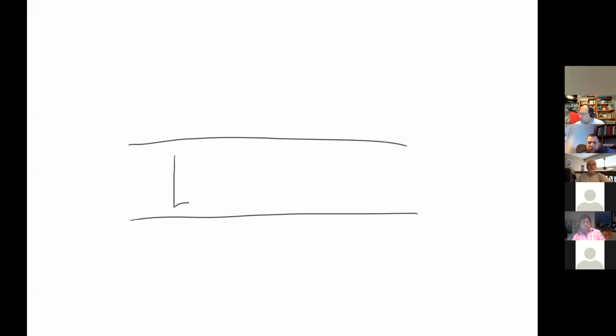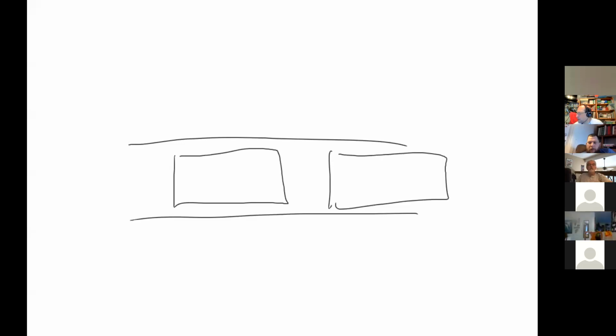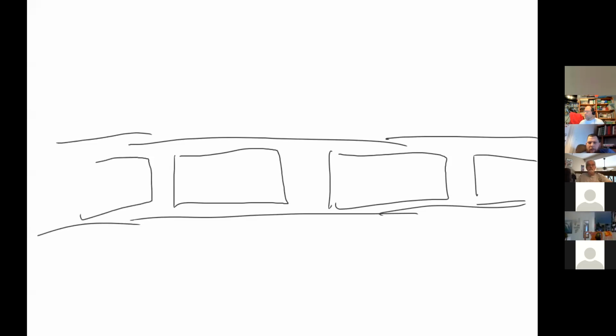You can also have transmission line that's just 2 parallel wires. And if you put plastic around it and make it look like this, it's known as TV twin lead or just ladder line. And if anyone remembers having rabbit ears on their TV, that's what this is. That has an impedance of 300 ohms or maybe 450 ohms, depending on what you got. It's just basically 2 wires in parallel in a plastic jacket, and that's known as ladder line or twin lead.